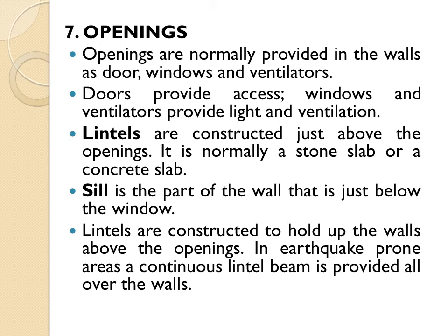So lintels are constructed just above the opening. It is normally made of a stone slab or a concrete slab. As we have seen in that figure, a lintel level is shown and also the sill level is shown. So sill is the part of the wall that lies just below the window.